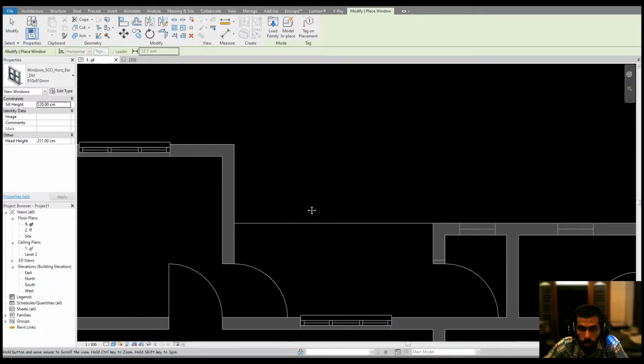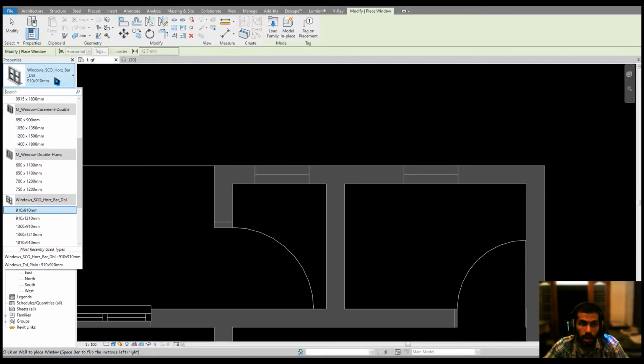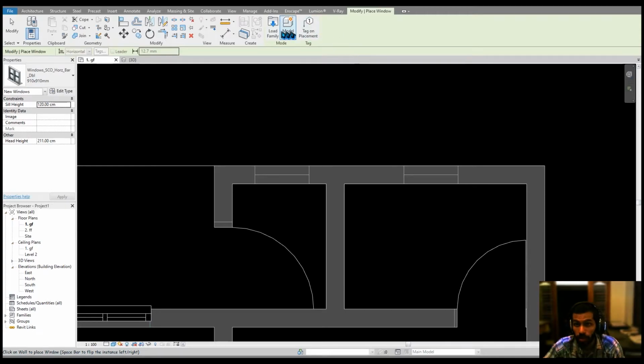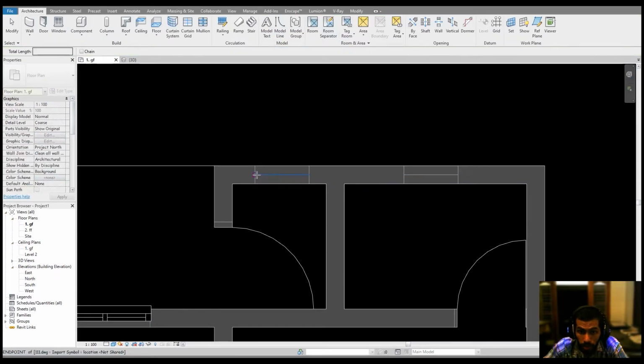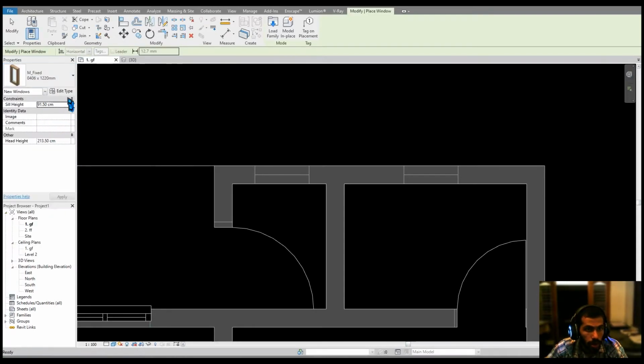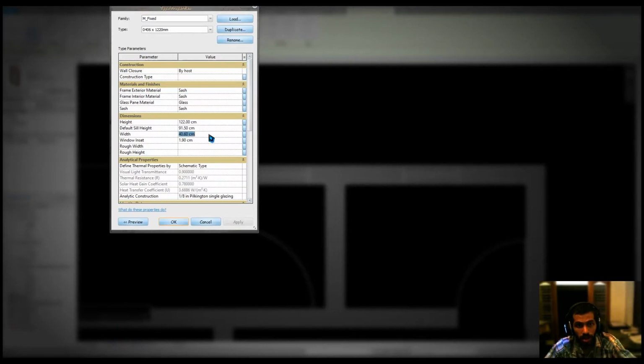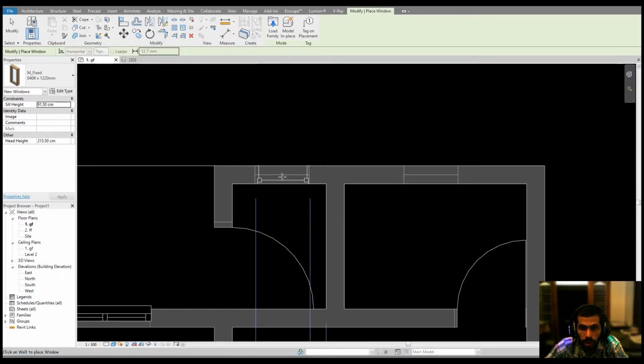So that's all about placing the 2-panel window, and we are having some ventilators here. Before placing, I'd like to know the size of it, and from first point to second point, that is showing 60. Okay, so window, I think, well, get into here, and I'd like to change the size, maybe 60 here, and I'd like to place it right in here.